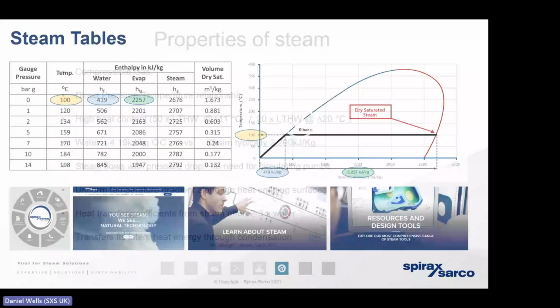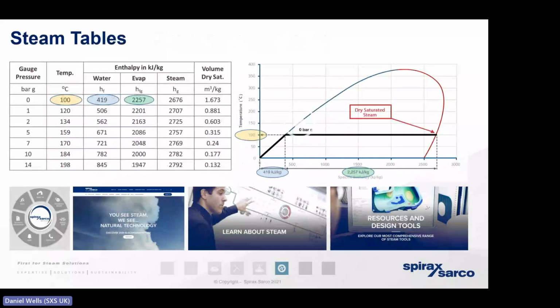So we've gone through the steam tables previously. And in the previous 3 presentations, we've taken our time to explain the relationship that the steam tables have and their importance. I'm going to skip through these very, very quickly. So moving from the left-hand side of the screen towards the right, the first 2 columns, they really demonstrate that pressure to temperature relationship. If we know the temperature of the steam, we know its pressure, and vice versa.